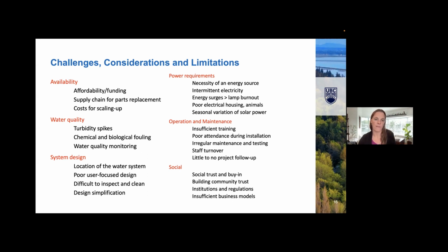Also chemical and biological fouling. This wasn't just with the wastewater project where they had fouling and scaling of UV lamps, but lamps that are submersed in the water will have that issue where there's chemical and biological fouling. So how can we anticipate that? And what's the appropriate cleaning schedule for cleaning the lamp sleeves?